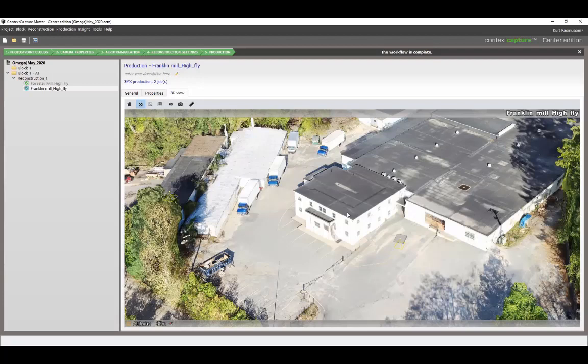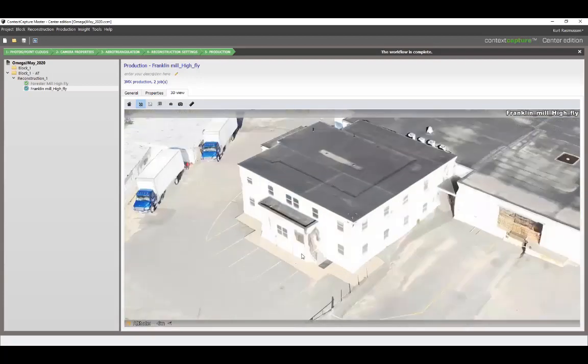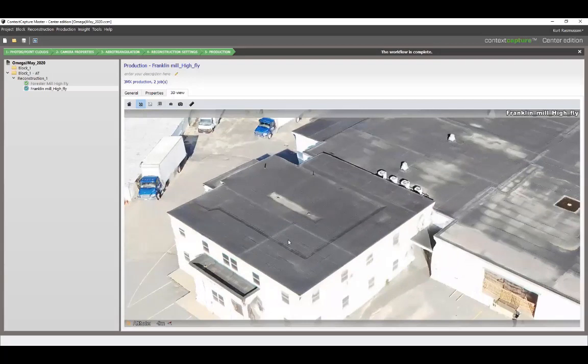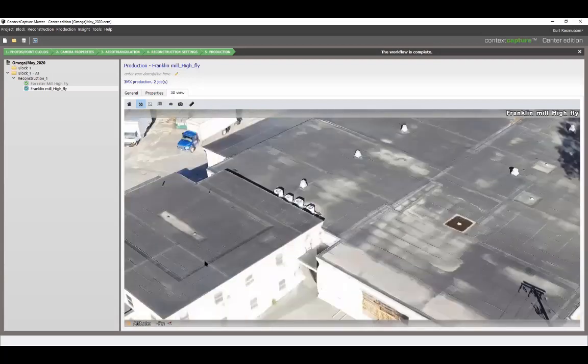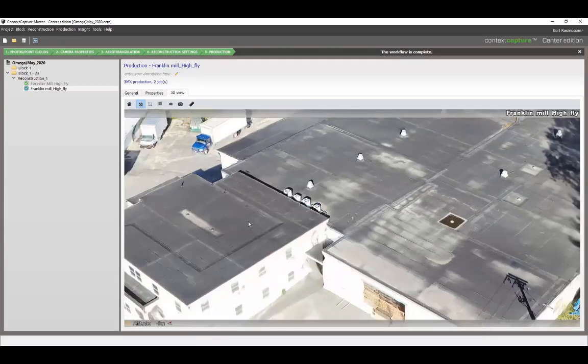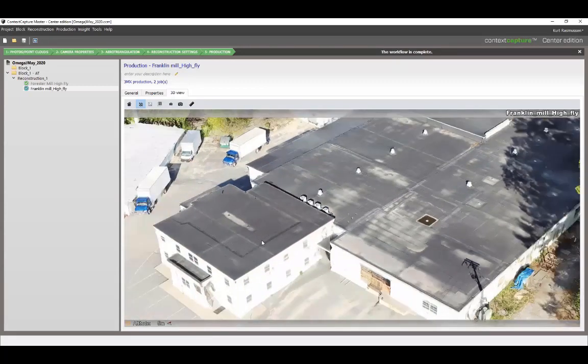Textures like steel beams may look like they have holes through them. So it's always good to be able to look at an area and then look at the original photograph just to confirm how it really looks. One problem I ran into with our software is I kind of feel that the mesh looks better than the original photo, and I don't even know how that's possible, but you'll see some examples. This one I flew pretty high. I think I was about 185 feet.